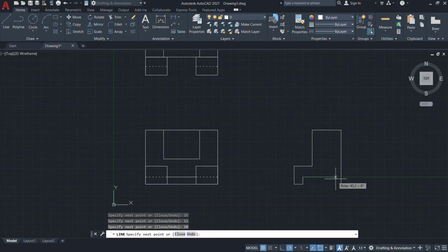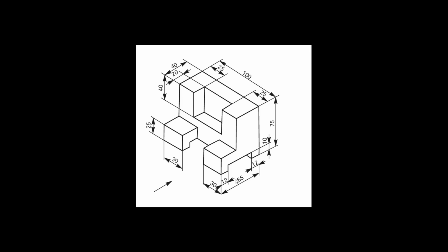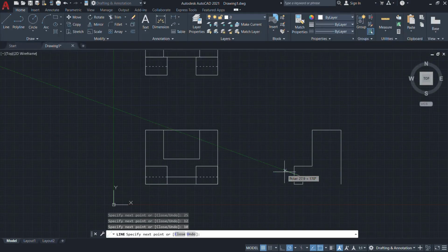Based on the 3D model drawing, I have clearly drawn these three different types of 2D projections. The horizontal line is nothing but the dimension of 65 minus 24. We get the value of 41 mm. So mention 41 mm horizontally at the right position itself. Again, the vertical dimension is 10 mm. Then close this entire profile on the drawing.